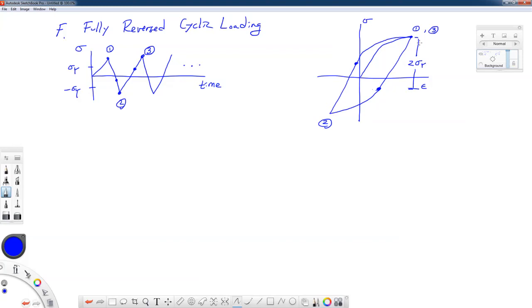So if we went up to 600 megapascals, we could even have yielding, in this particular example, before we're even in compression. We have yielding on the reverse side. This is an experimental observation, okay? And it's known as the Bauschinger effect.